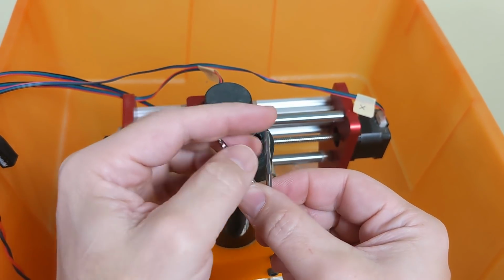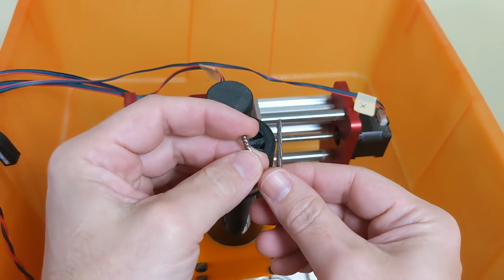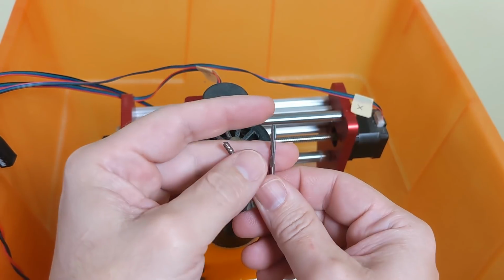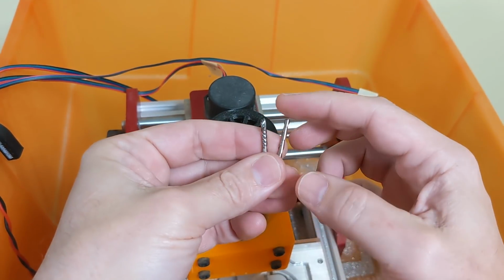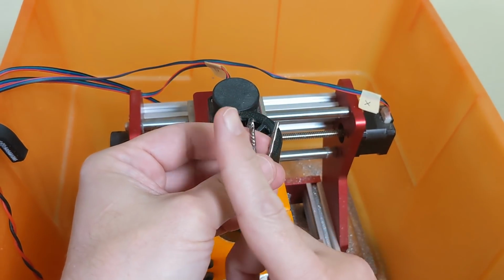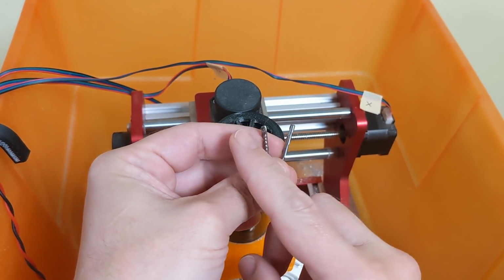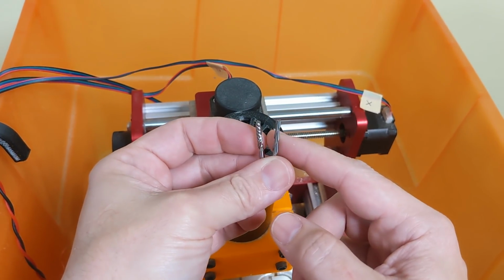It breaks. So the 2 fluted bit here is going to be stronger than the single fluted bit, and it's true of 4 fluted bits. They're even stronger still, although there is a diminishing return there. But the point here is that a single fluted bit has only a single cutting edge. So with each revolution, you only get 1 cut. A double fluted bit gets 2 cuts for every revolution.